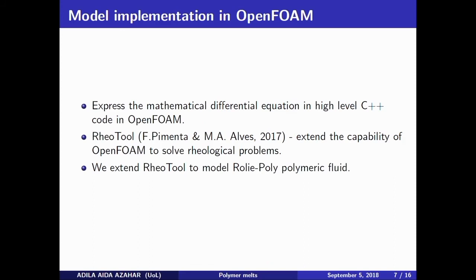So what we did is implement equation 3, the Rolie-Poly model, within the OpenFOAM software, where we can translate the complex mathematical model into high-level C++ code in OpenFOAM, and we use the RheoTool package, which extends the capability of OpenFOAM to solve rheological problems.